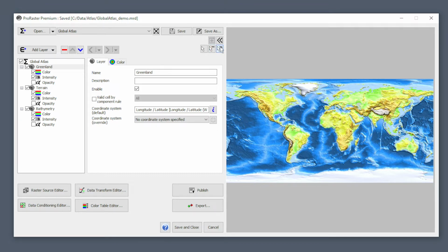This third button gives you a more verbose report. So now it's telling us the value, and it's also telling us the raster that value is coming from, and then in brackets the field name and the band name, and underneath it's giving the X and Y coordinate. In this case it's longitude and latitude.